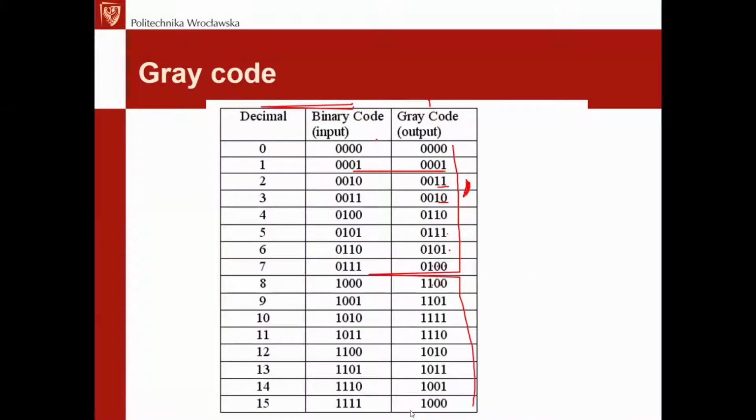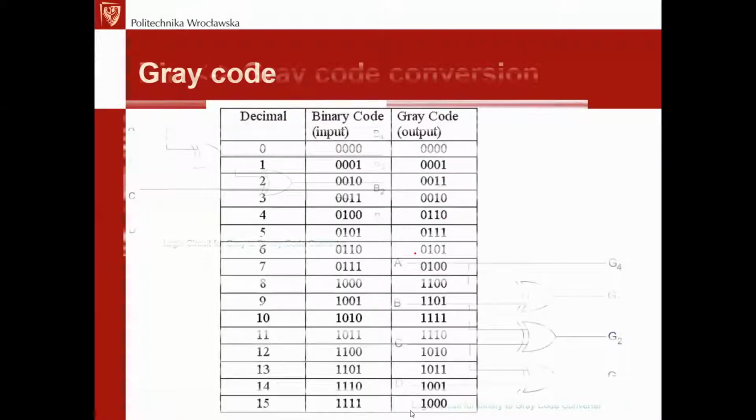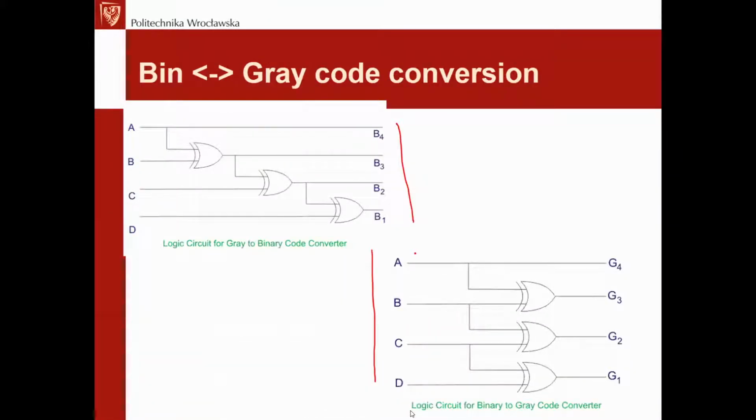Although it looks very complex to decode, and you might wonder about a very complex algorithm for doing this, on microcontrollers we decode it with lookup tables. That's simple. While electrically, we decode it with just 3 gates.